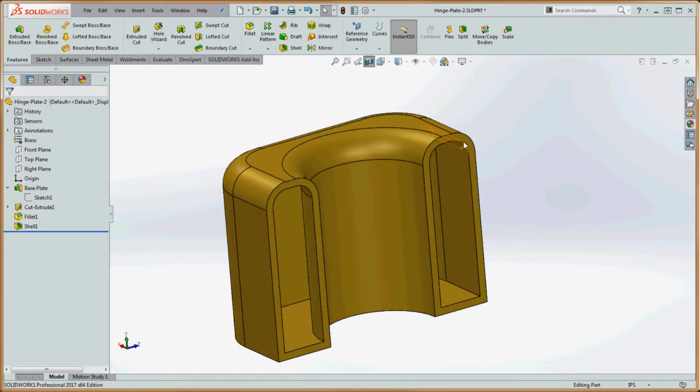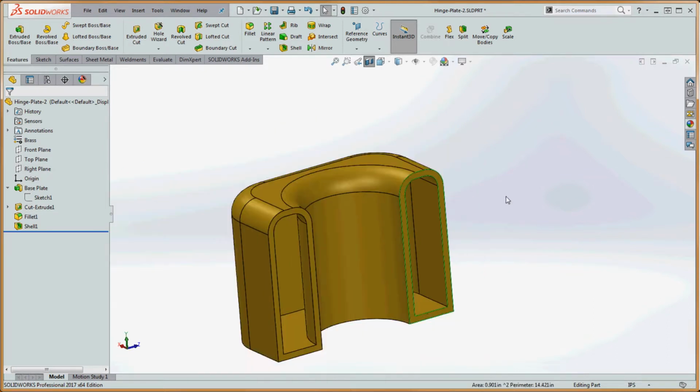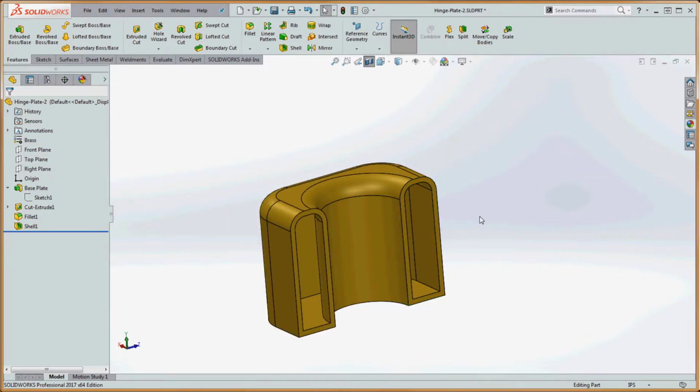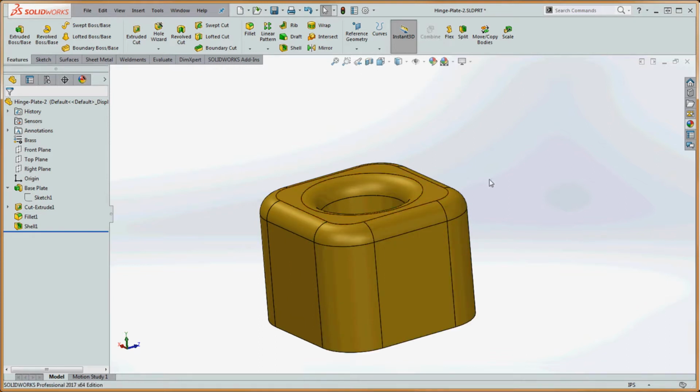Now you might think that if you section this, you might be able to select that as a surface in order to do some additional modeling on. I don't think SolidWorks will allow you to do that because it really isn't defined in the model. It's kind of defined in a peripheral way. But you'll notice up here in the heads-up view toolbar that the selection tool is still kind of gray. The button's outlined, so it means it's selected. If you want to deselect that, get that out of that section mode, just go ahead and click on that.